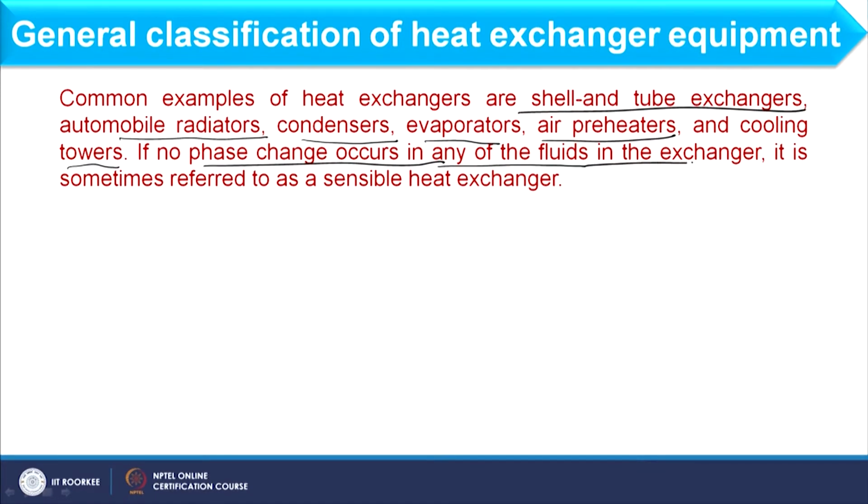in any of the fluids in an exchanger, it is sometimes referred to as a sensible heat exchanger. When I am dealing with liquid and liquid, or air and liquid, where phase change is not occurring, we can say that only sensible heat transfer occurs. Such heat exchangers are called sensible heat exchangers. If you see the classification in a subsequent slide, the classification is based on phase also. Sometimes it is single phase and sometimes it is multiple phase.